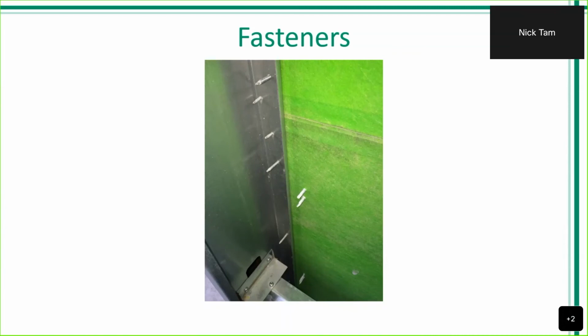But one thing to note is that ASTM D1970 and E331 are tests that relate to materials in perfect conditions. But are we really going to rely on the potential self-sealability for thousands of penetrations going through a wall? More than likely, that's not going to be the case, and we'll typically see particular treatments of these fasteners going into the membrane or on top of these fasteners after it's already been installed.